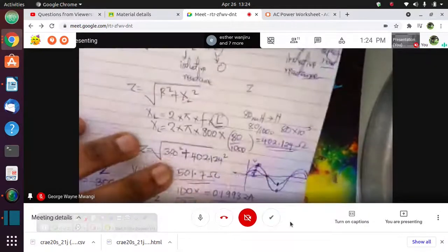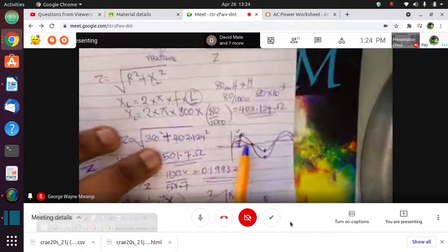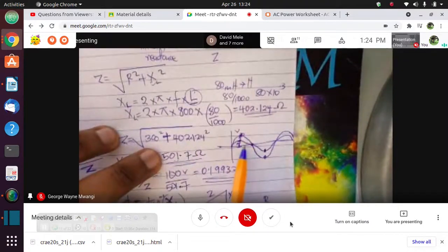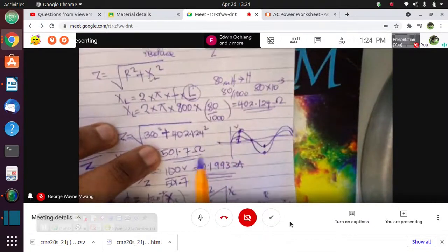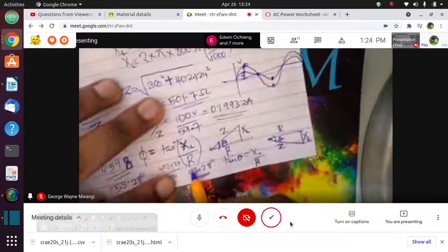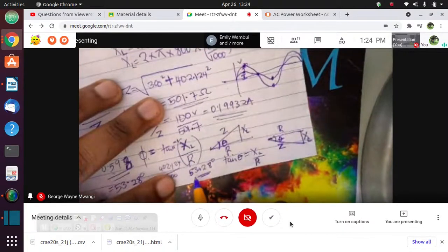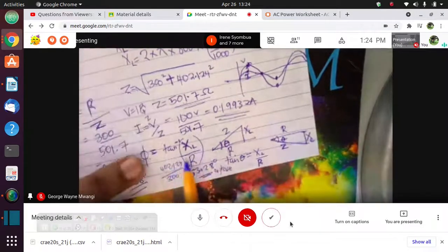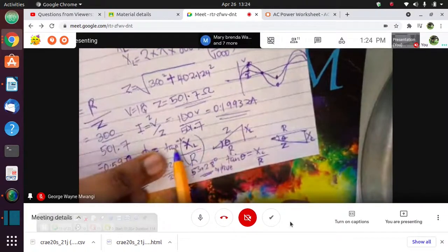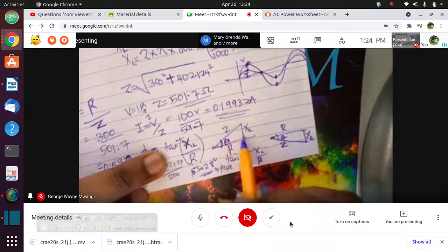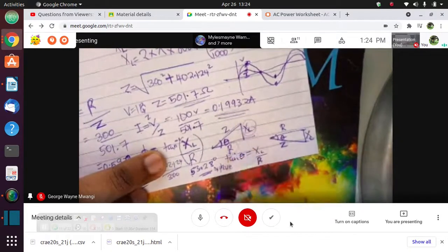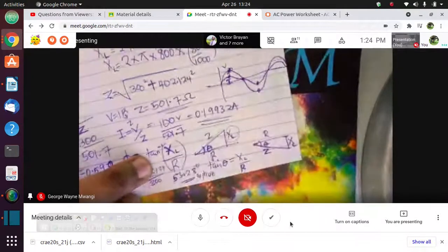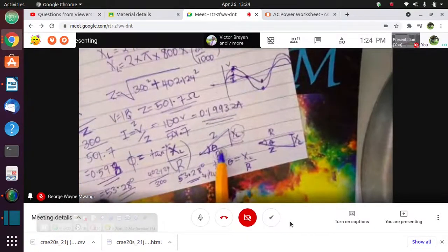But when you introduce things like an inductor and a capacitor, this changes. So you find that the current or the voltage will be lagging or leading the other. And that angle that shows that the current and voltage are leading or lagging each other is known as the phase angle, and it is found by taking the tan inverse, in this impedance triangle, of this divided by this. Are you together? When you take the tan inverse of that and that, it will give you the phase angle.